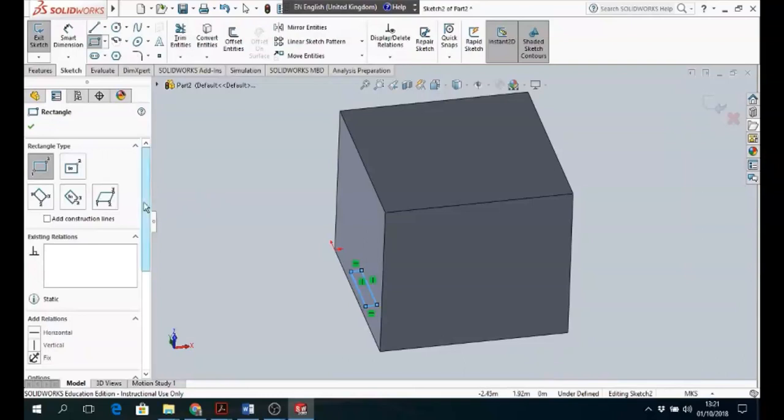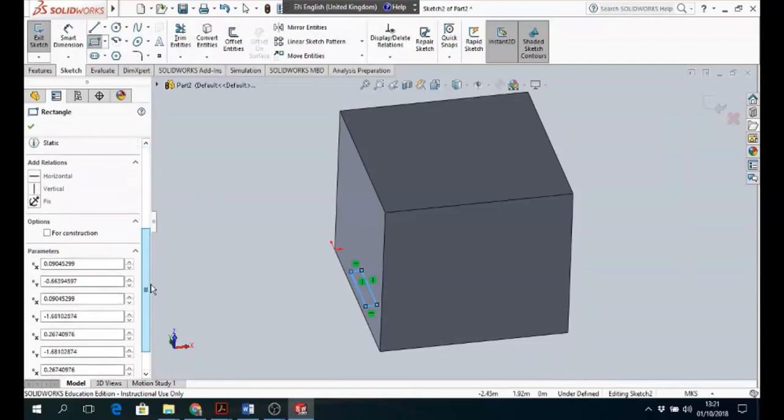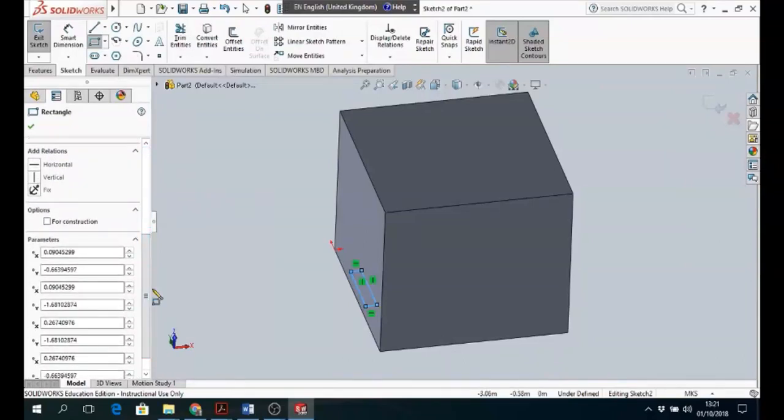And if we go to the parameters of that, we want to get that to go from x is equal to 0.05 and y is equal to 1.3 as one corner, and x is equal to 0.15 and y is equal to 1.7 is the other corner. So next, change that to 0.05, and for the local coordinate system, this is going to be minus 1.3.